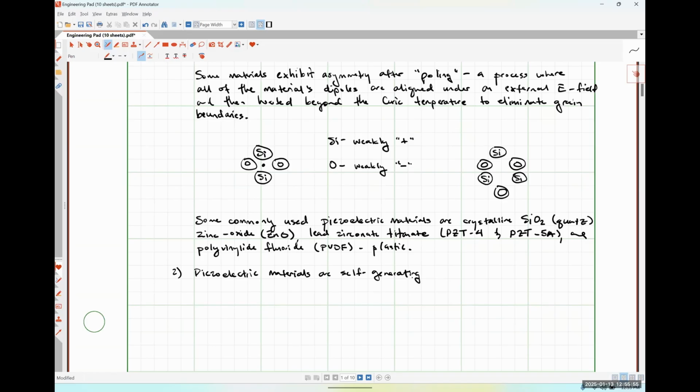That will not exist for piezoelectric materials, or doesn't have to exist, let me phrase it that way, because they're capable of generating their own electrical fields effectively. The compression generates a field, which in turn causes a voltage. And so we're good from there. So the signal that is output from a piezoelectric material does not require external power supply or anything like that.